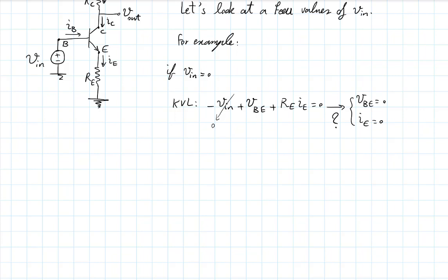Well, imagine you have a positive IE, which requires a negative VBE from this equation, right? But a negative VBE means that that diode is reverse biased. That contradicts a positive current going through it. So that's something I want you guys to pay attention to. In this particular problem, maybe that's a small trivial thing, but this will become important in other problems. The reason I can make this conclusion is that a positive VBE here cannot live with a negative IE and vice versa, because the diode will allow current only in that direction once on.